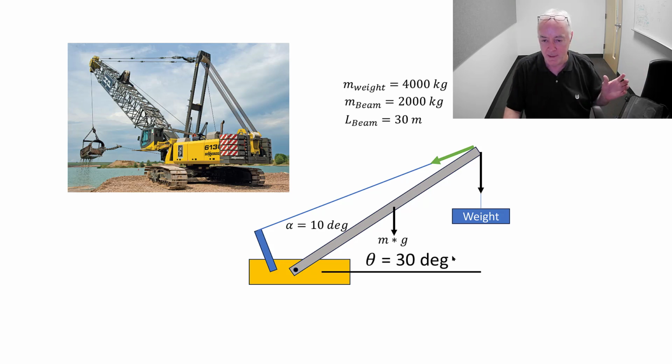So I schematically put together the useful information, right? And I'd say the angles are particularly important. The basic questions are what's going to be the tension in the blue line, and what's going to be the forces carried by that pivot point right there. Think of it like a bearing, right? And the general strategy is to resolve these vector forces into components that are useful for us.